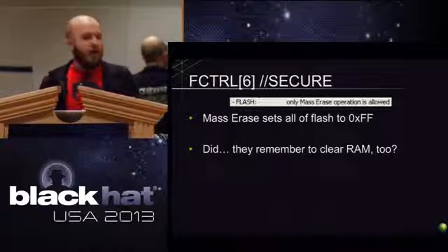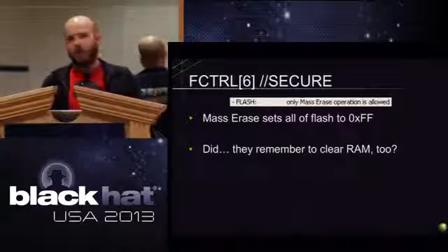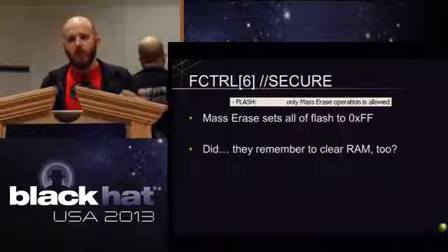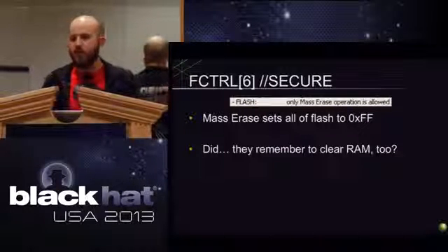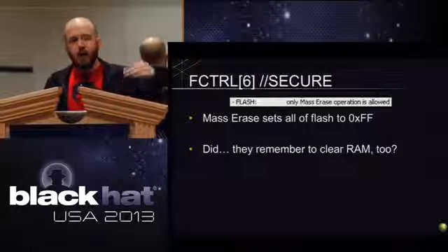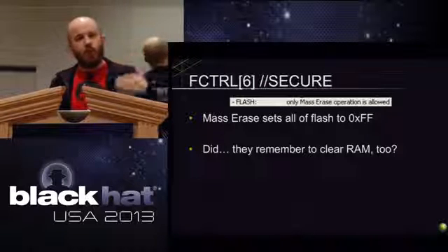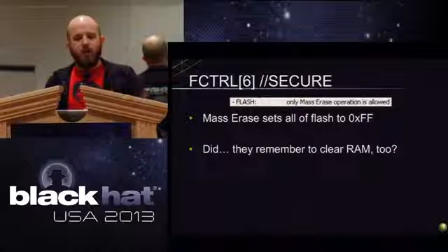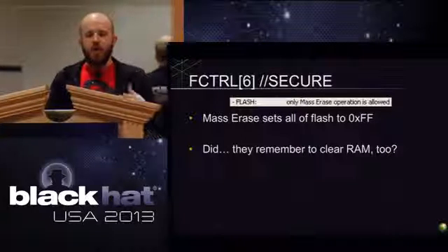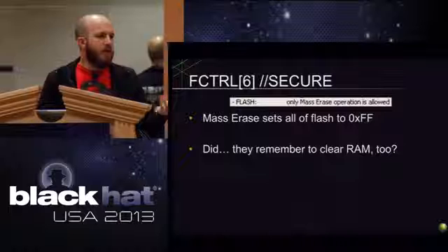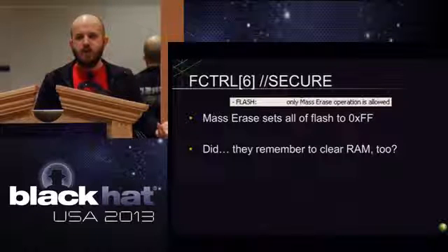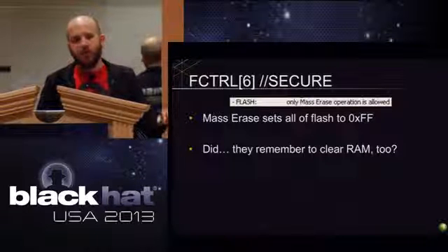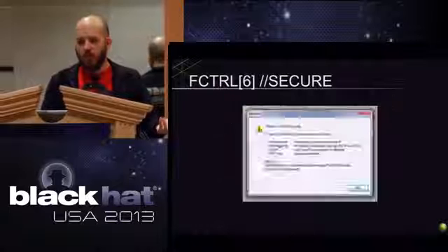So how do you get back into that device, right? They didn't want to just have that be a bricked scenario. So the common way that these guys will do it, and MSP430 does it the same way, and others, it'll let you, without being able to light up the full debugging interface, perform a mass erase. So what does that do, right? It resets all the flash to FF, but there's an important consideration here: did they also think to clear all the other locations? Because that's not the only location where something sensitive is stored.